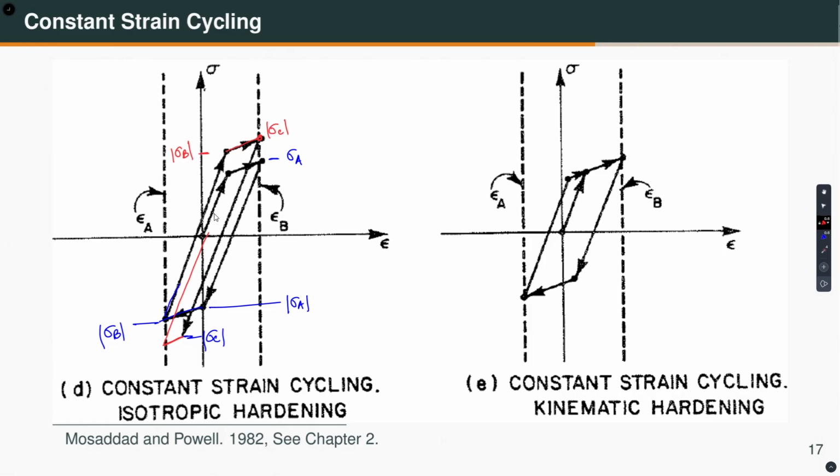On the other hand, the kinematic hardening, what it is showing, is that you go from here to this strain. Then when you take it back, it must yield early, because this must remain your 2 sigma y. And then you go this path and again like so. So, it is again able to predict a stable hysteresis loop.